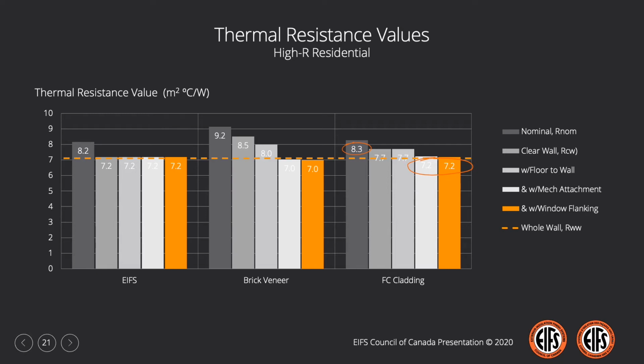Without getting into too much detail, I'll refer you back to part 1 of this series where we looked at terminology and specifically the impact of continuous insulation and its mitigation on thermal bridging. One of the other benefits of exterior insulation is the lifting, if you will, of the effective thermal resistance of all of the insulation inboard of it. What we also see with higher insulation amounts on the exterior is a reduction in the impacts of mechanical attachment losses through that insulation. So the thicker the exterior insulation, the better the overall wall assembly performance translates into.